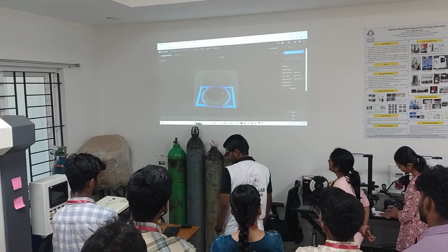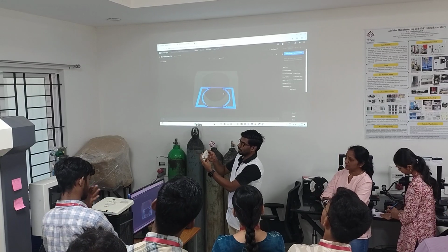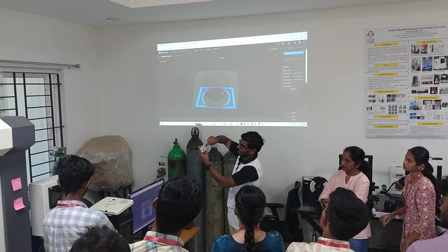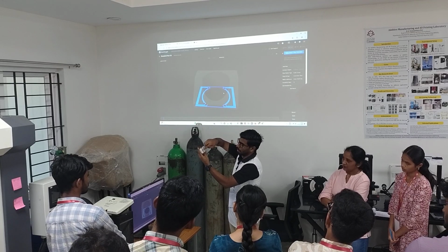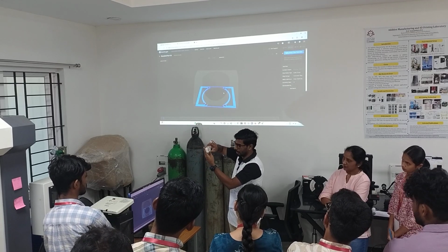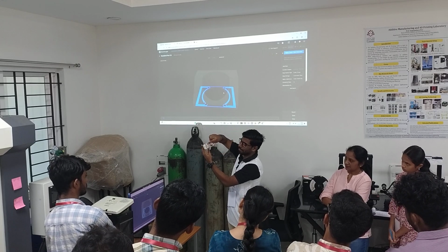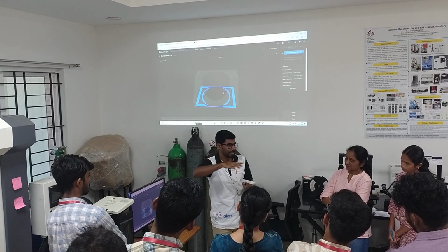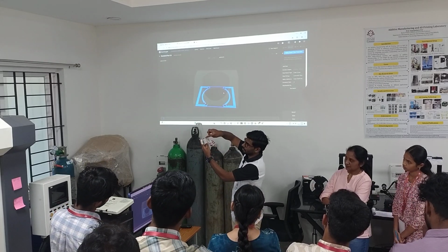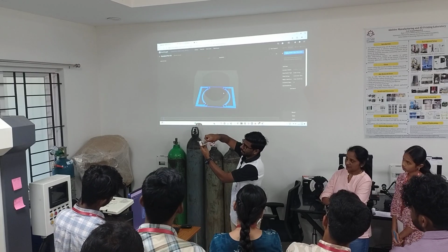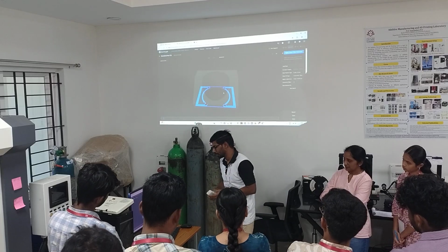Concentric basically means, if I want to print this, the fiber is aligned along the wall, along the periphery of this object. Then it is called concentric. So we'll go like this. This is a very basic thing we know from FDM printing and this slicing software. Concentric means it will go like this. Isotropic means it will have zigzags, a honeycomb or something else.